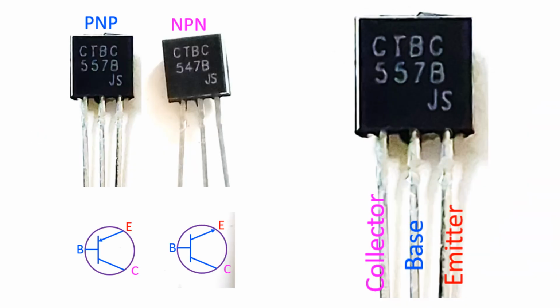Currently, two basic types of transistors in use are the field effect transistor (FET) and the bipolar junction transistor (BJT). Terminals of the FET are named gate, source and drain. Voltage given to the gate can control the current between source and drain in the case of FET. Terminals of BJT are named base, collector and emitter. Current at the base terminal, which flows between the base and emitter, can control or switch a much larger current between the collector and emitter.